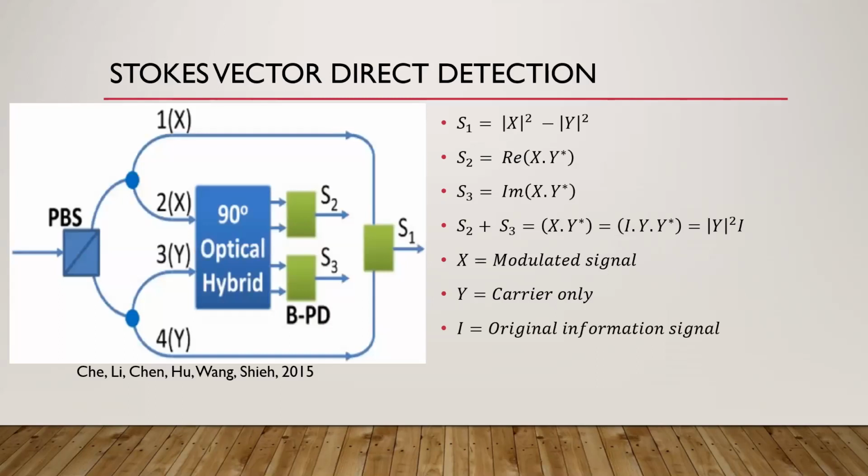So this is one of the most simple circuits that we can use for that. What we've got on the left-hand side coming in is the combined signal. So that's the transmitted signal, coming into a polarization beam splitter. That's splitting the signal between, say, the X and Y polarizations. Both of those are going into optical couplers, which just split each of those X and Y signals further.